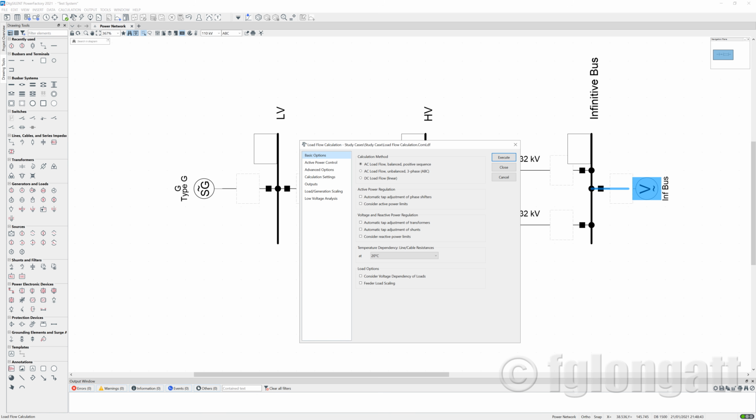And as you can see, this is the command load flow calculation. You can see here at the top, at the title, ComLdf. And that is the command load flow, okay? This is the command that we use for a steady state analysis, and I will not change configurations here, okay? Because I want to run the classical AC load flow. In this case, we are using positive sequence for the model of this transmission system. There is no problem. That is what I want, positive sequence balanced.